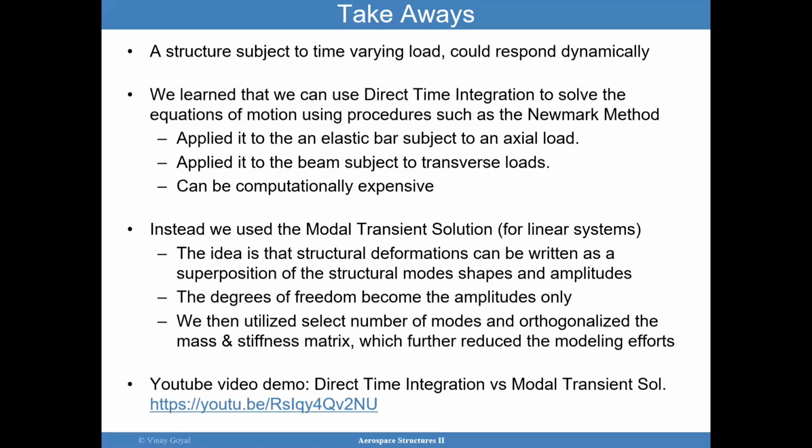So since the mode shapes are fully known because I found them through the modal dynamic procedure or frequency extraction procedure, then the only thing that I really don't know is the amplitudes that need to go along with each of these mode shapes that when combined make up the full aircraft dynamic structural behavior. So the degrees of freedom then simplified just to amplitudes.